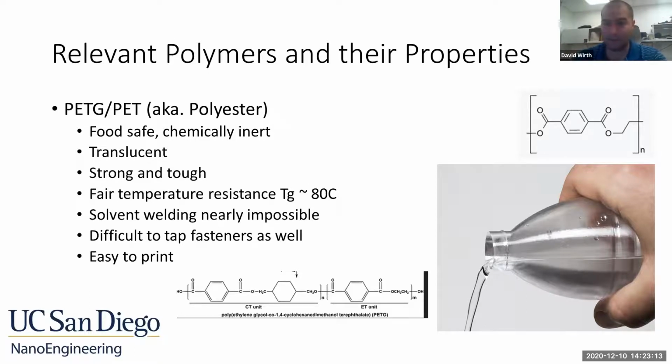A lot of people will try to print this stuff on a PEI bed, and if you try to print PETG on PEI without a removal layer, it will rip your bed up. So yeah, this stuff adheres very tightly.